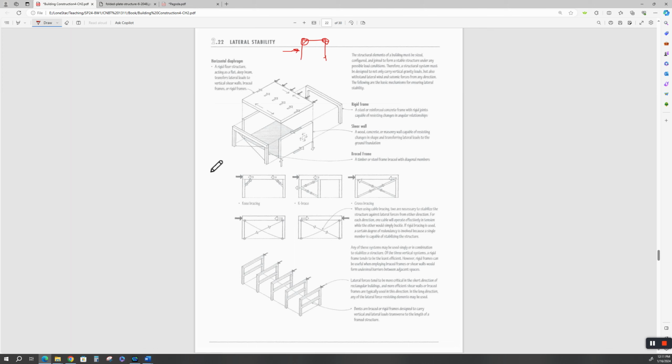Any of you have ever done any traditional stick framing, like for a residential house? Even though you get the frame all up, you can still make it creak and rock a little bit when you're pushing on it. But when you start putting plywood siding on the outside and stitching it to the frame, here's the frame. All this is nailed together. This is on the bottom plate.